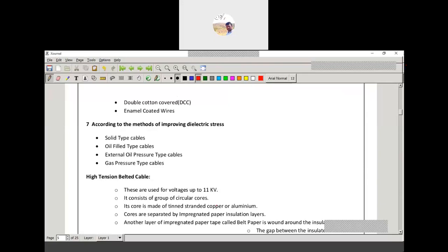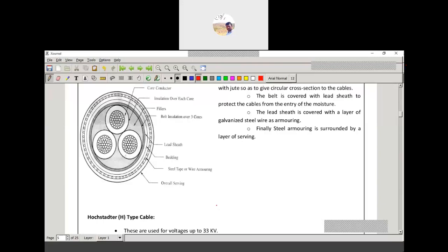Next we have the PVC cable. Generally, what we are using now is the polyvinyl chloride cable, which is insulated with PVC. It consists of a copper conductor with polyvinyl chloride insulation around it. It is affected by temperature, therefore it is not suitable for heating applications. It is for interior and domestic applications only; where high temperature is there we cannot use it.